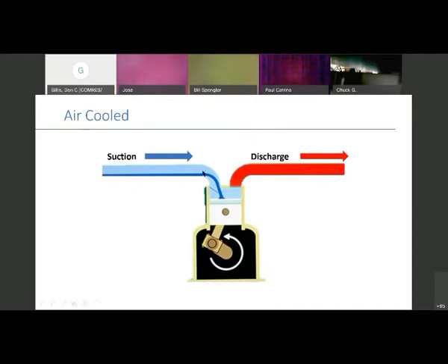Notice here on the left-hand side, that suction line coming in at that head, we'll call this the K-body. The dark blue indicates the liquid refrigerant coming in. The light blue is vapor. So obviously, common sense would tell you once this comes in with liquid refrigerant, we're going to get a lot of damage or some scarring up here in between this piston and this cylinder wall.